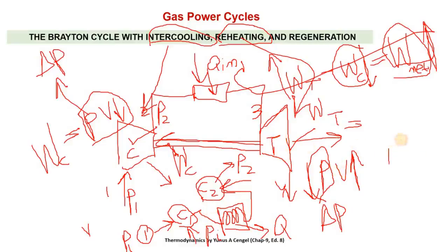So this is point 3, fluid is entering, which is a gas, in first turbine T1, and work is obtained, WT1. Now its pressure is dropped from P3 to some intermediate pressure Pi, because in the turbine pressure will drop because work is extracted.